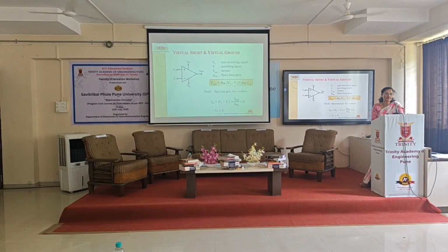And what about the ground concept? If non-inverting terminal is at the ground, as per the virtual short, inverting also is at the ground. Now, this concept is very useful while going for the derivation of voltage gain equation in linear application. And no doubt some practicals are there related to the linear application, integrators, differentiators are included.